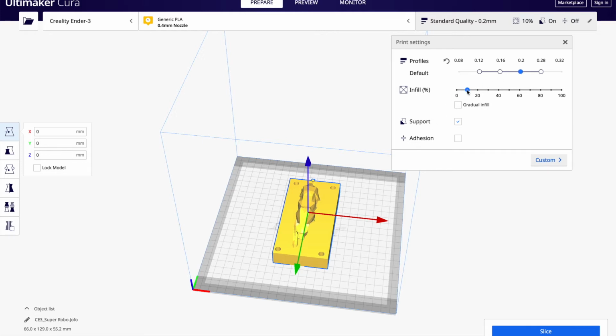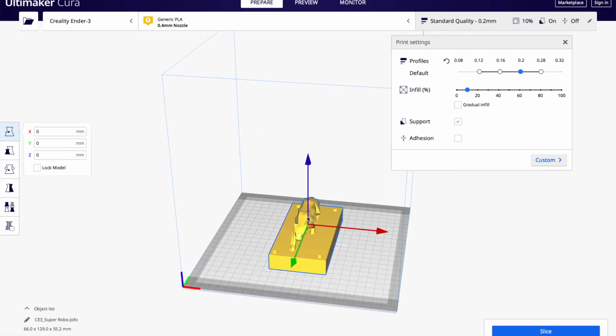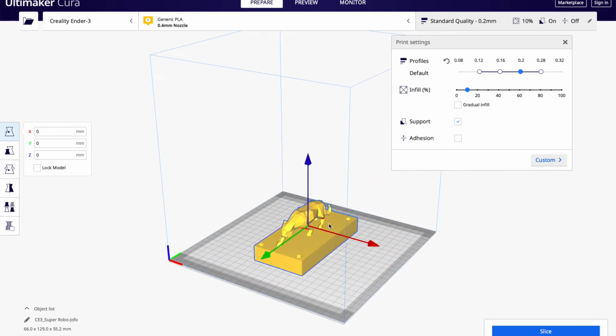So, the next big parameter is infill. Infill depends on how much material is inside hollow objects. For example, this square, or inside of this panther, right? There are a couple of things. It cannot be a solid object for 3D printing because it's generally a waste of filament. So in order to change that, we can change the amount of infill.